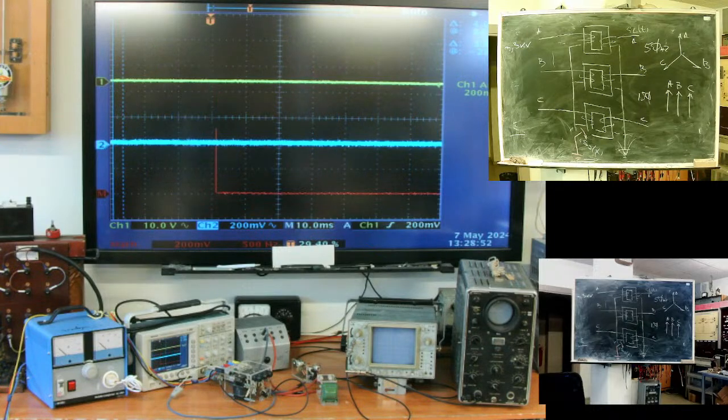At night, a disconnected neutral wire causes overvoltage and burn of electronics equipment. Daytime, everything is fine. No one sees the problem with a disconnected neutral, which can remain, say, undetected many days until voltage rises a bit, some 10% increase, and you're done.